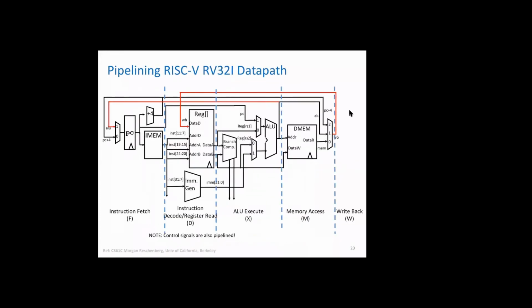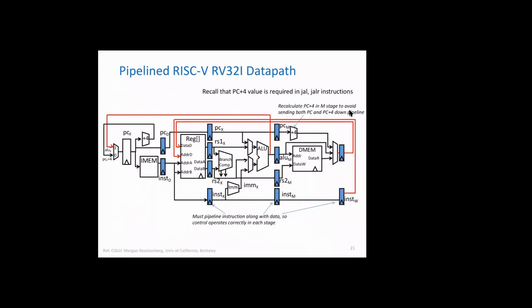All right. And now we actually put registers here. Okay. Look at it carefully. You can see some changes. Say, for example, we have put in one extra adder here. Note that we were doing PC plus 4 in single cycle design.